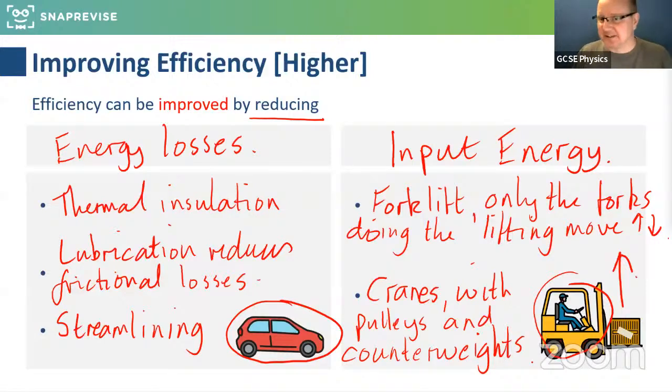And actually, that's how some railways work on seaside resorts, where you've got a flow of water like a river. They fill up tanks with water as a counterweight to balance the weight of the people getting on at the bottom. And when the tank is full enough, it becomes just heavy enough for gravity to pull the water down and lift the people up. And then once the people arrive, the tank can be emptied and the top station loaded with people. Well, not emptied, because the people will come down very, very fast, but some of the water reduced, and it can go up and down like that with minimal input energy, just using a natural resource.